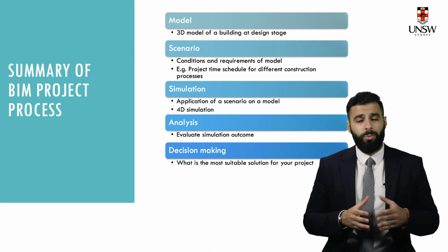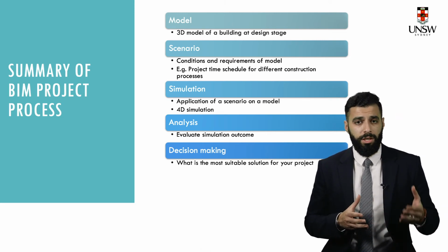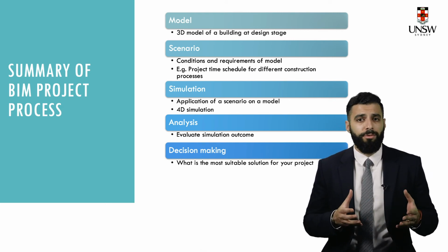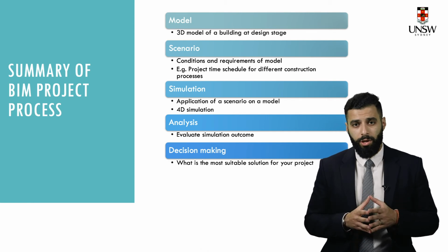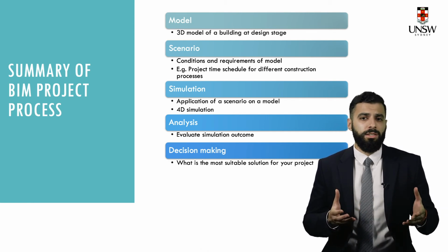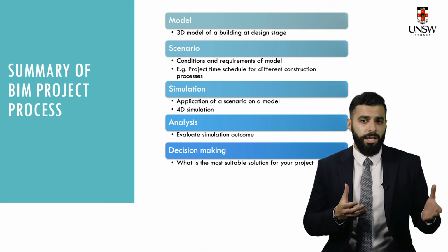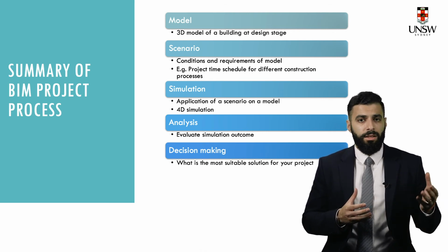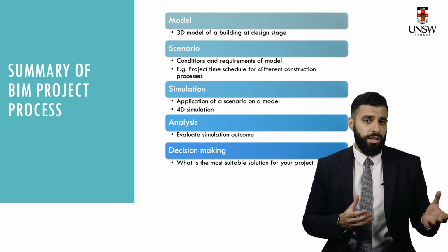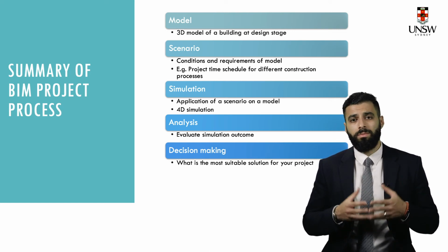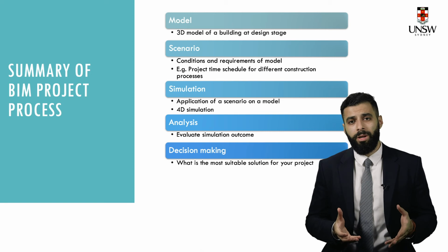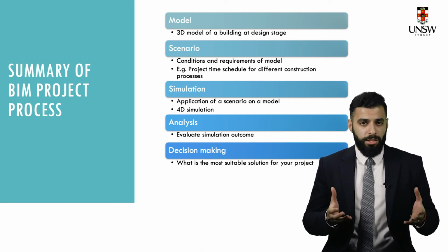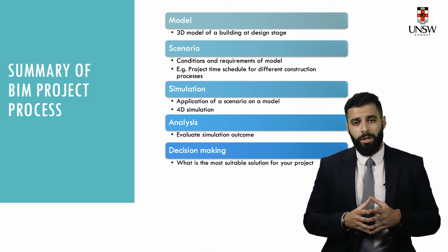The second step will then be implementing the scenario based on the decisions that you need to make. So for instance, how will traffic go in and out of the site? Where would you place your access gates? And how would the locations of these gates impact the pouring activity of concrete? So that's all part of the second step in that framework that you see in front of you.